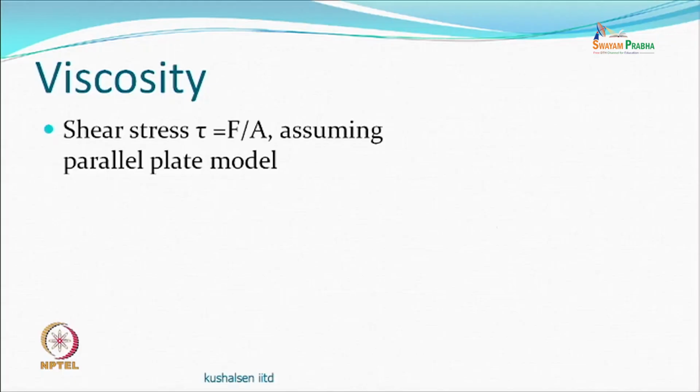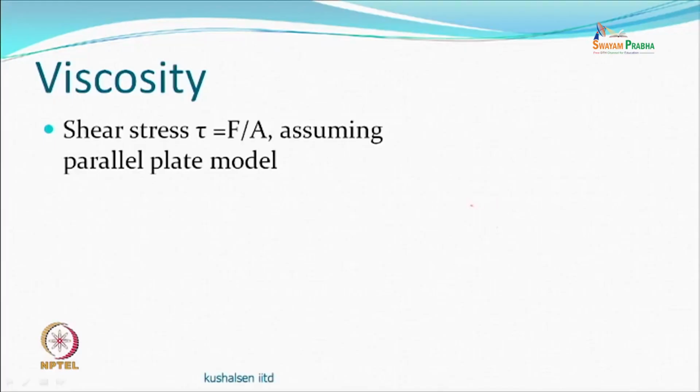So, from our point of view, viscosity, as you may have understood earlier also, is basically layer by layer shear happening in a system. The way it is defined is, you have a shear stress. The parallel plate model may be represented something like this. It is assumed as if one layer or plate is moving, the other may be stationary.